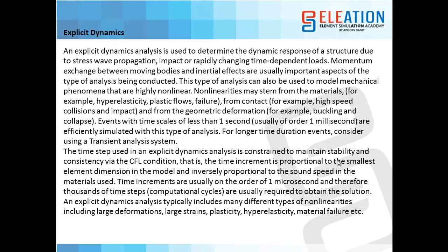Events with a time scale of less than 1 second, usually of the order of 1 millisecond, are efficiently simulated with this type of analysis. For longer time duration events, consider using a transient analysis system. The time step used in explicit dynamic analysis is constrained mainly to maintain stability and consistency via the CFL condition, which we will see later on. That is, the time increment is proportional to the smallest element dimension in the model and inversely proportional to the sound speed in the material used.